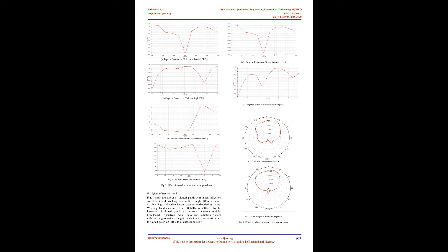3. Design mechanism. The design methodology for the proposed antenna array is based on the coupling mechanism between cylindrical DRAs of different permittivity and a center-fed network structure for exciting the array elements through the modified coplanar waveguide feed. The design procedures have been summarized below.